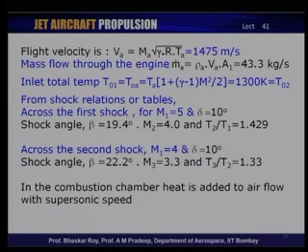per second. In view of the very high inlet velocity, the mass flow going in is also very high, even though the density is of the same order and the area is of the same order. The inlet total temperature can now be computed from the isentropic relation that you are familiar with, and this gives us a total temperature of 1300 K, which is conserved through the intake duct.